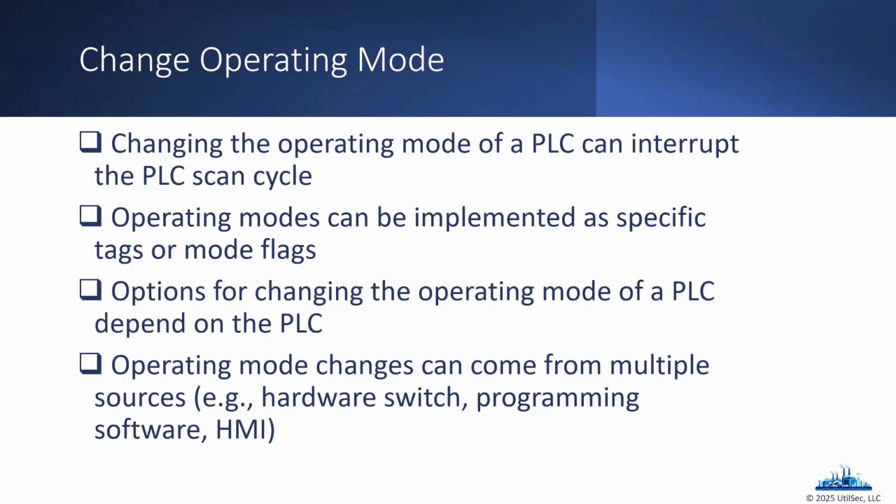Now, you can do it through the programming software. Remember, programming software is dependent on what vendor you're using. So if I'm going to take a Siemens PLC from run mode to remote program mode, I have to use the Siemens software to do that. So we have to have access to the Siemens software. And then is that software going to ask you for things like usernames and passwords? You have to be prepared for what if you are actually asked for credentials. Of course, to get there, you probably had to get on a system that also required credentials.